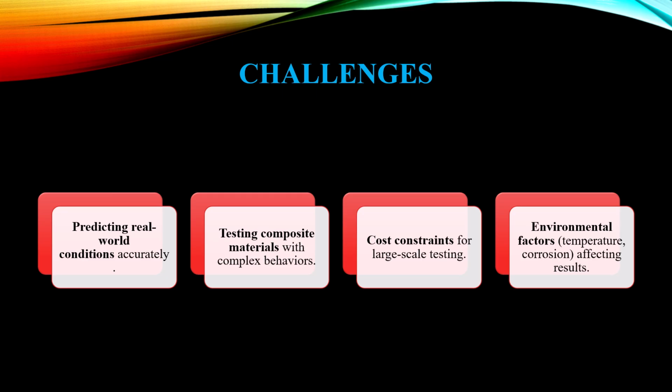Challenges. Conducting effective fatigue testing presents three major challenges. First, accurately predicting real-world conditions remains difficult due to the complex, variable nature of operating environments. Second, testing composite materials is particularly challenging as their anisotropic properties and complex failure modes require specialized approaches. Third, researchers face significant cost constraints while scaling up tests to match actual component size or testing volume.